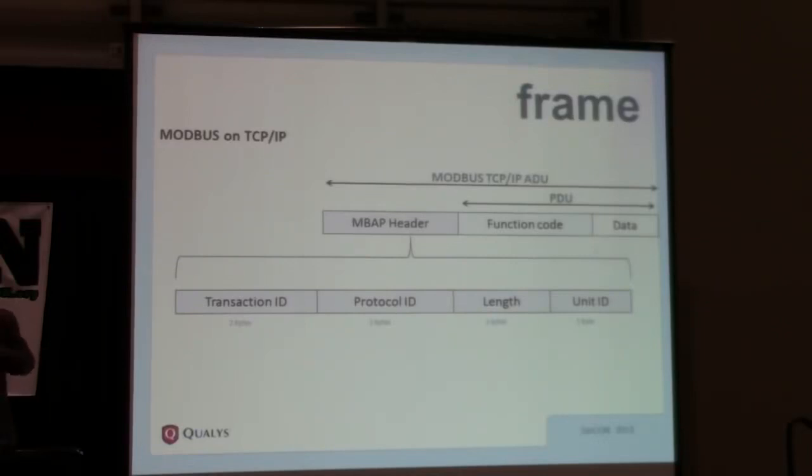When someone asks you a question, you say, okay, this is question number 1, this is question number 2, and that's exactly what a transaction ID is. Protocol ID is fixed for Modbus. Length is the length of the packet, and unit ID is something interesting.